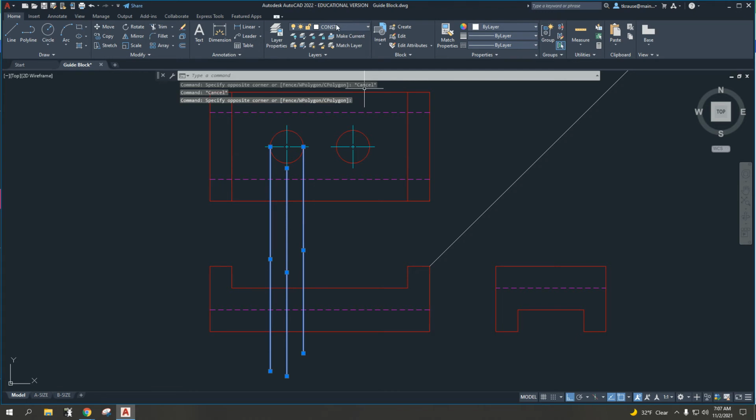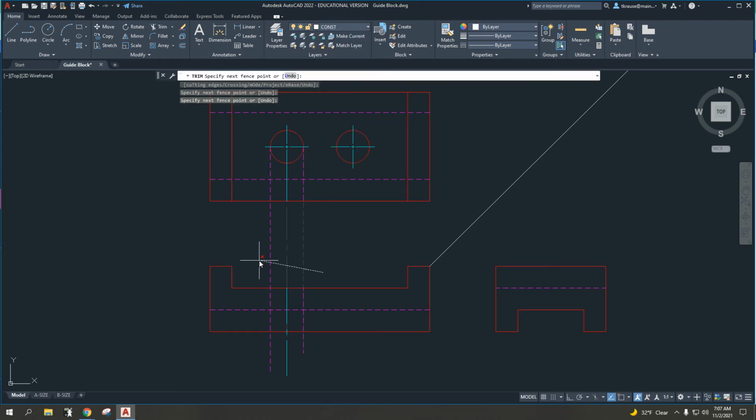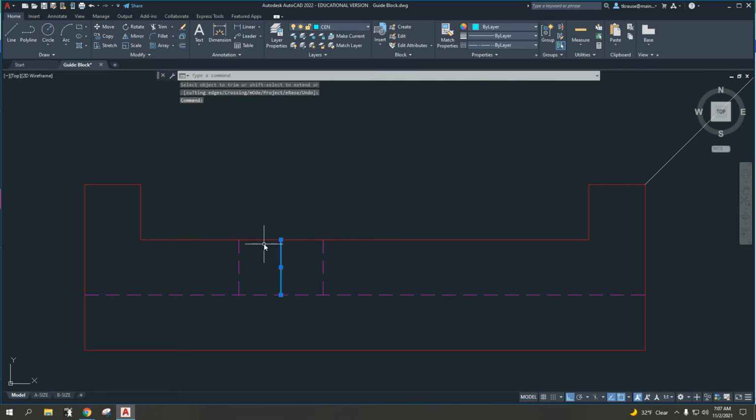So then some people, again, this might work for you, might end up changing layers and trimming, like you see here. Let me get rid of that. Oh, do it down here. Okay. Oh, and I trimmed those incorrectly. So let's get rid of those. And then, again, one of the common things is we need to see a dash here. And on previous drawings, a lot of people aren't extending the center mark beyond the edge of the object. The hidden lines should stop here, but the center mark should extend beyond the top and the bottom surfaces by, let's say, about 1/8 of an inch.